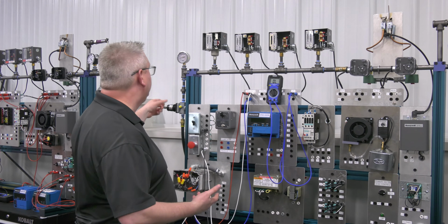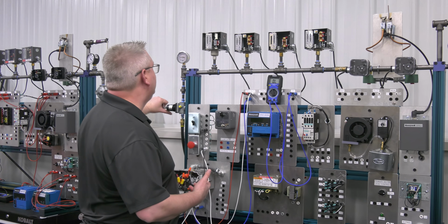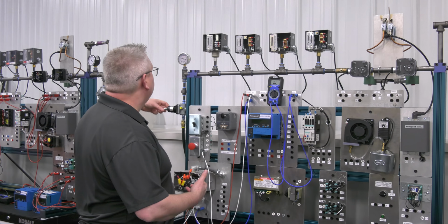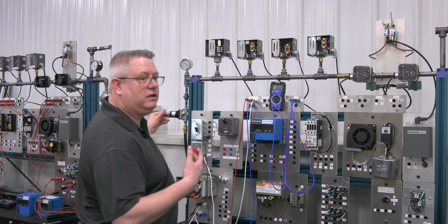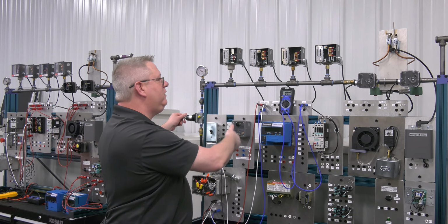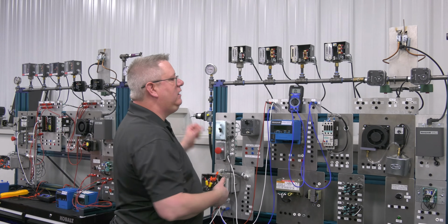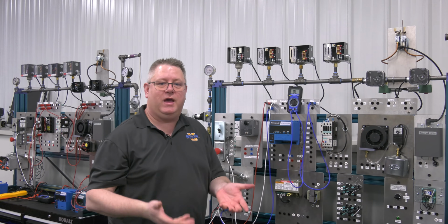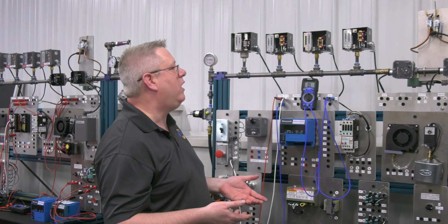So I'm going to increase the pressure on this. It's set for 50 psi. And it cleanly made at 50 psi. And so if that was wired into our modulation circuit, what we would see was that once that circuit made, our mod motor could ramp up and do its job properly.